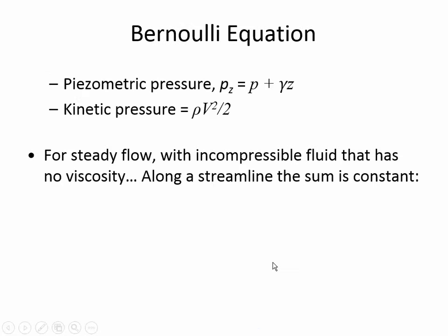So models are useful. And back to the idea of the Bernoulli equation, the assumption, steady flow, incompressible fluid with no viscosity along a streamline, what that tells us is that the sum of these two terms, the piezometric pressure and the kinetic pressure, are equal. Now let me show you the other way that we were looking at Bernoulli's equation just a moment ago, which had units of meters. So we had the pressure head, elevation head, and velocity head was constant.